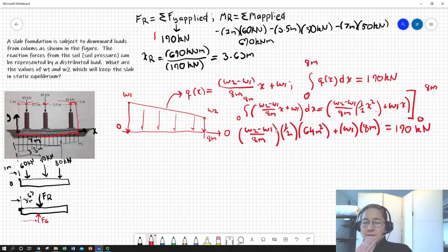Now at this point, what were we trying to evaluate? W2 and W1, these load distribution values for these 2 points under the slab, because that's going to be linked back to soil properties that we can then dictate when we tell the guy with the compactor to go out there and get our soil bearing capacity, what it needs to be.